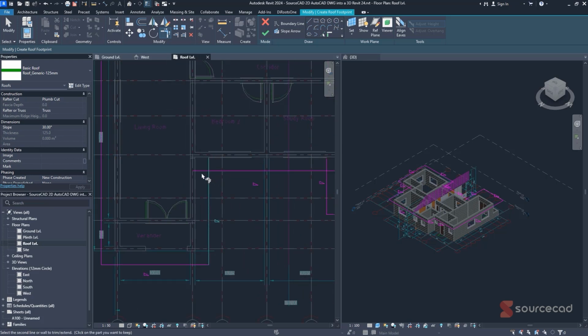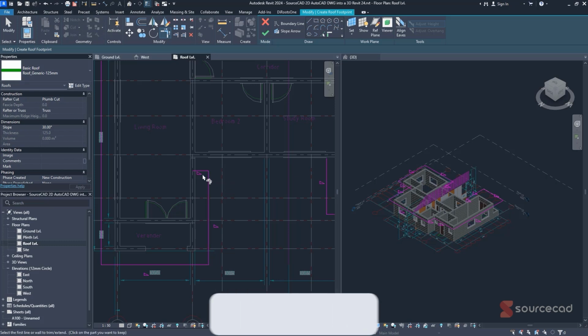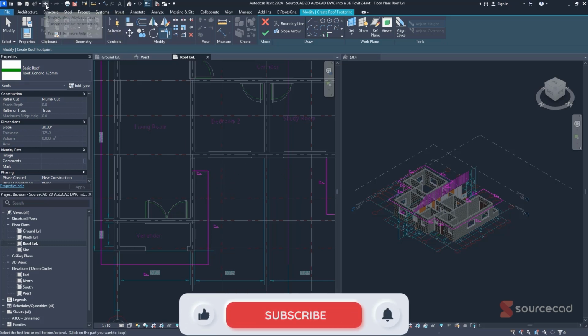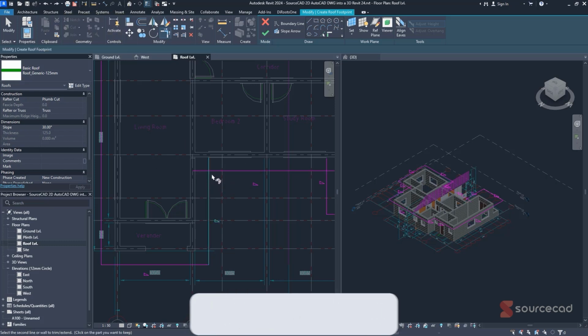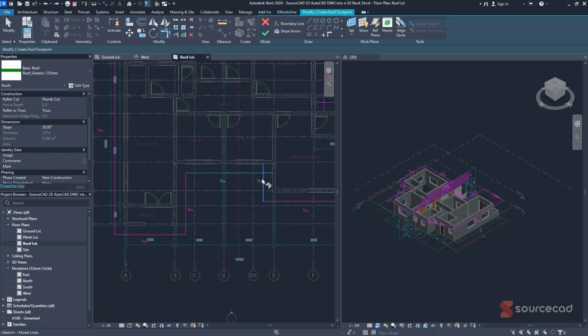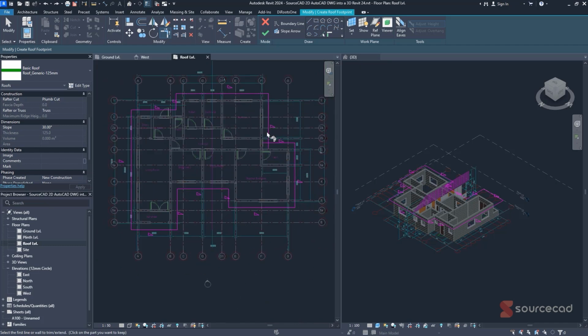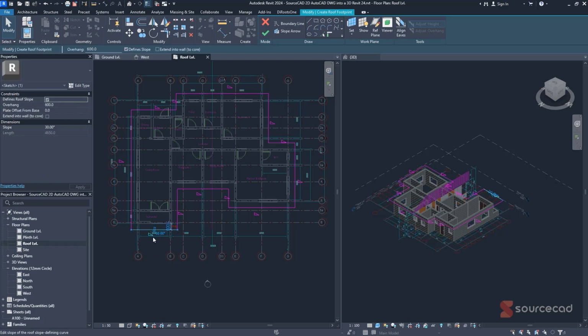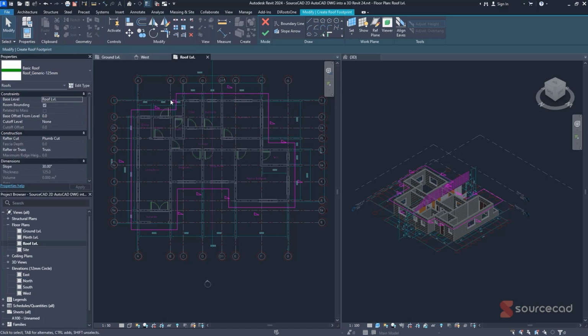So you have to be careful. In the event I click on this side, it will delete my roof or my extrusion line on this side. So if you want to select your corner, it's gonna give you a guided dashed line like so, and you're gonna know which side to select, just like that. Last place here. So I can fine tune things. Over here I don't need the slope to be here. It can be a gable. So this side hipped like so. I am satisfied with that.